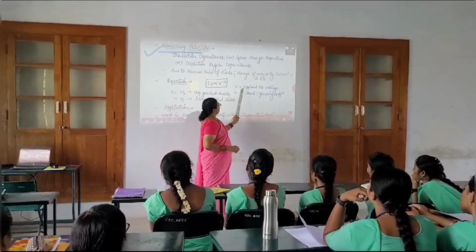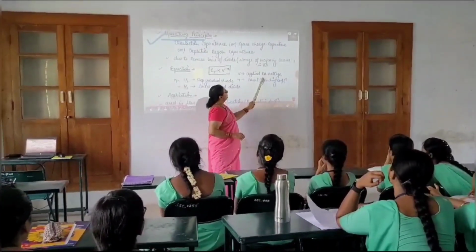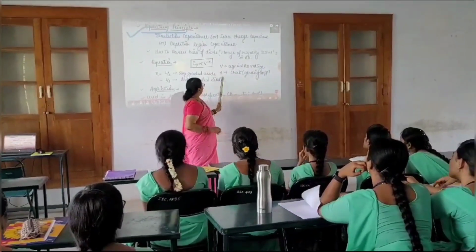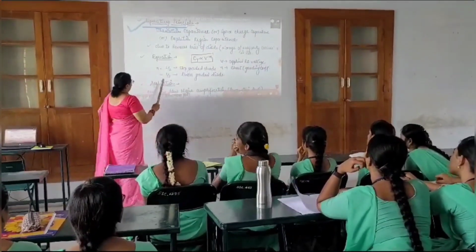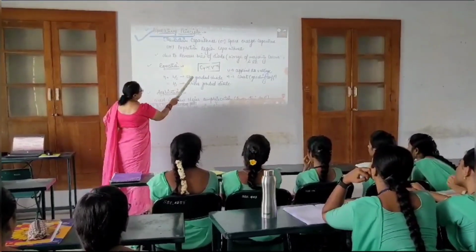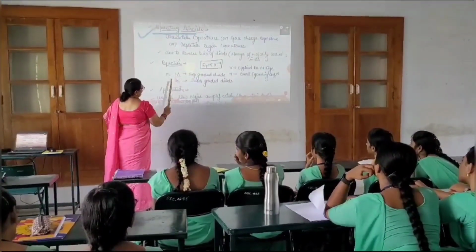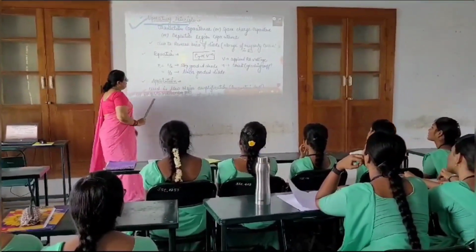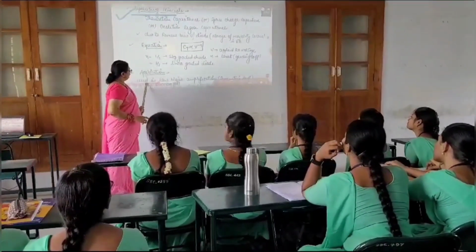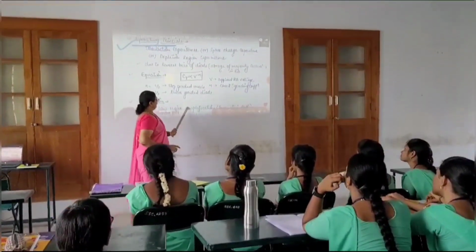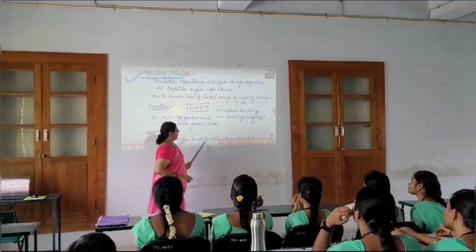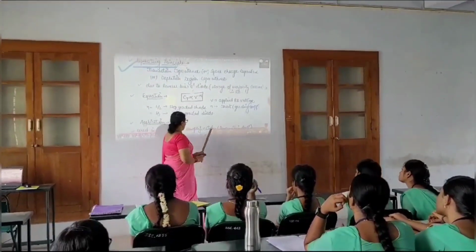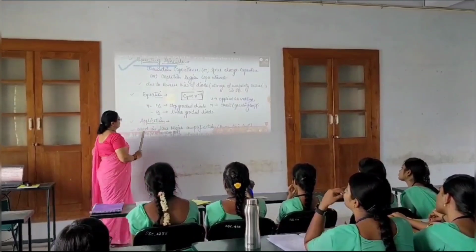Further from the circuit, it is evident that the output voltage is fed back to both inverting and non-inverting input terminal. At resonant frequency, the voltage applied to the inverting and non-inverting terminals will be equal and in phase with each other. However, even here the voltage gain of the amplifier needs to be greater than 3 to start oscillations and equal to 3 to sustain them. In general, these kind of op-amp based Wien bridge oscillators cannot operate above 1 MHz due to the limitation imposed on them by their open loop gain.